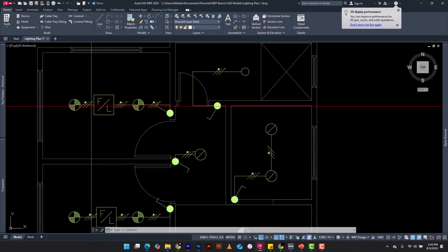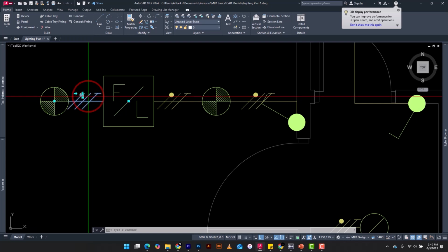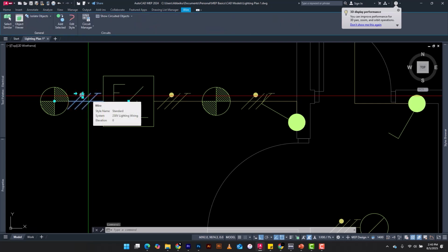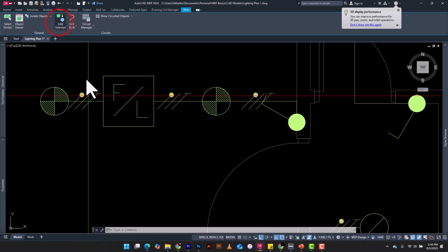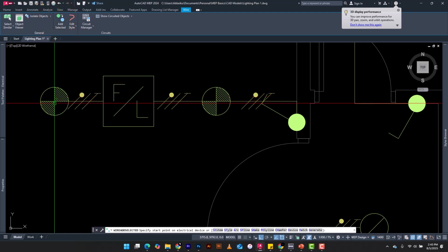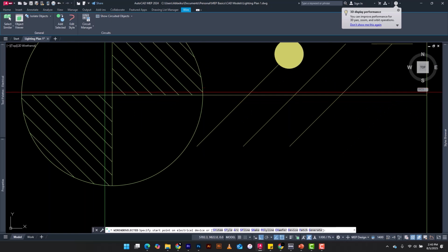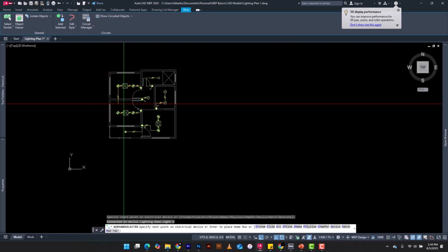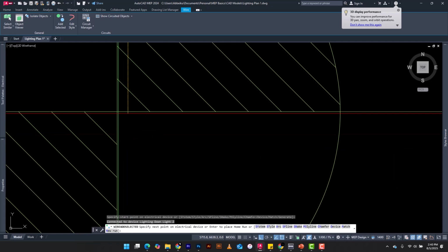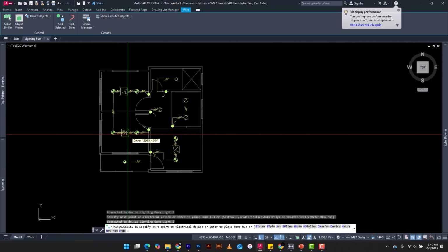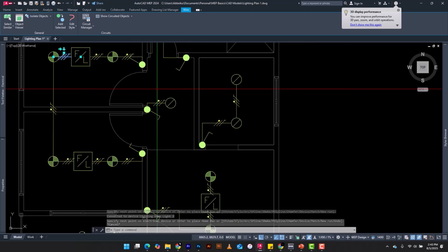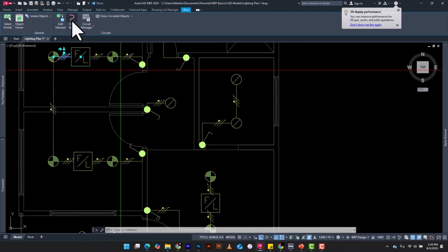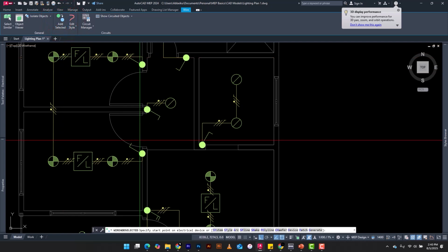Okay, so what I'm just going to do is to show the connections and something we call home run. I'm going to show you shortly. So basically what I'm going to add is connect these systems together. So I'll add similar. Again, look at this, make sure that I connect to the end connector. I'll select this and I'll connect this to this lighting fixture here. Okay, now after doing this, I'll come to this place. Okay, I'll add selected again.